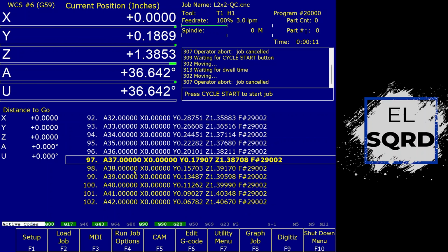In cases where the arc is lost after ignition, meaning the torch did start but the arc was interrupted mid-cut, the process is more difficult. You can't ignite mid-path. The torch must restart at the beginning of the cut path. This may be problematic because the material is already partially removed, and this often prevents the arc from re-establishing, so it may arc out again for lack of material. Try it at least once because it may work.